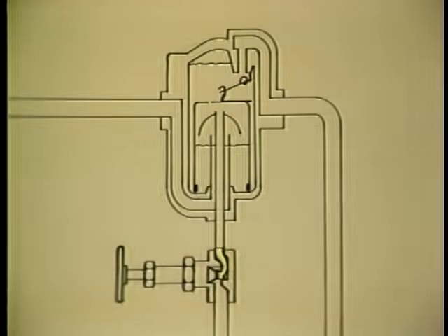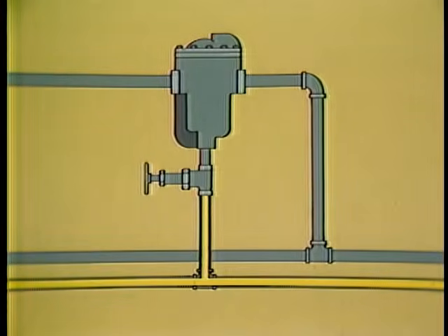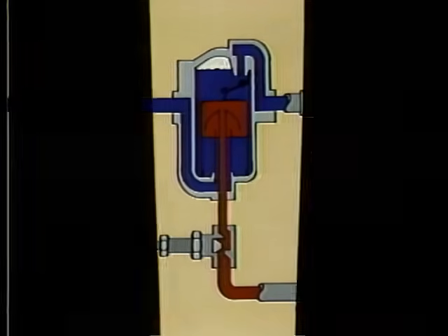The manual metering valve is adjusted to remove these gases during full capacity operation or to meet the velocity requirements for purging the system. The DC may be piped in one of two configurations depending on the job requirements. For secondary steam recovery, the discharge of the metering valve is piped to a separator and then to the top of a secondary steam header and transported to other workstations. If the flash steam and non-condensables are to be removed but not used in a secondary steam system, pipe the discharge of the manual metering valve directly to the condensate return line.